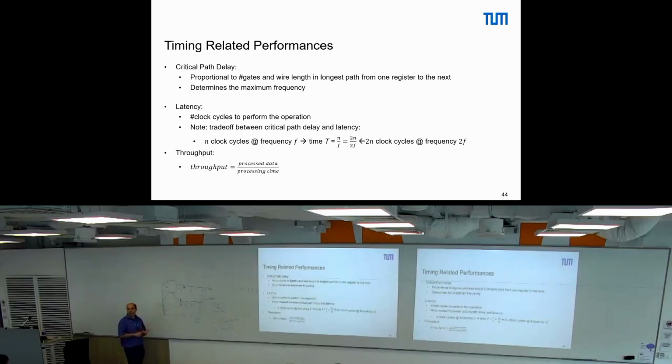Can we increase this? Do we decrease it? We decrease. Why? It's more clock cycles, that's correct. The frequency goes up because we have reduced the path lengths. It may be that if you do it like that, because you cannot just double most likely the frequency, your throughput goes down. If this allows you to double more or less the frequency, then it's the same.